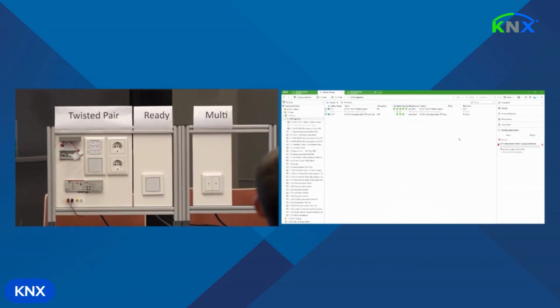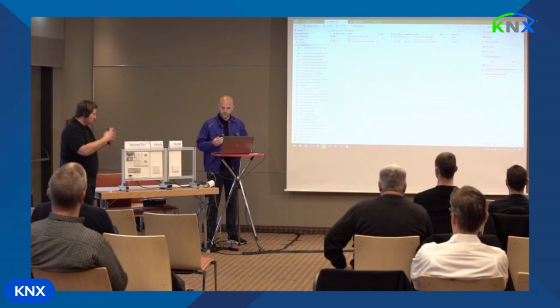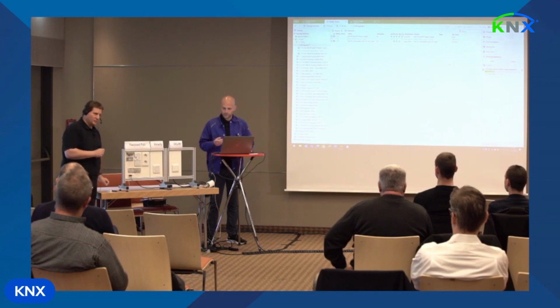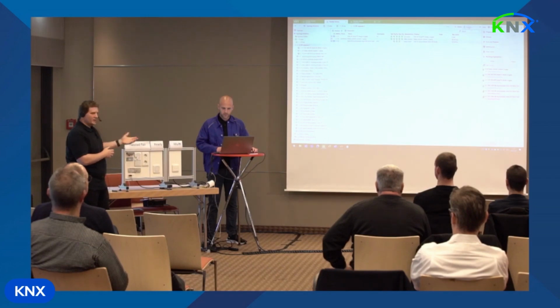So I had to activate the programming button on this device. Yeah, it's a unidirectional device. So if you want to program it, you have to wake it up manually. The new multi battery-driven devices are listening with this multi-SLE, so battery friendly, but still listening all the time. So you can wake them up via ETS. You do not have to do this manually.